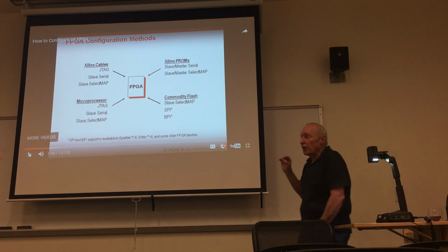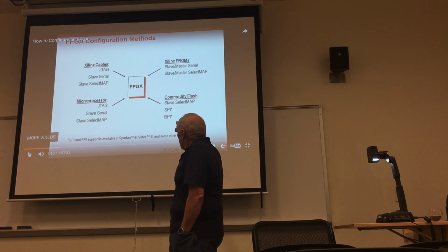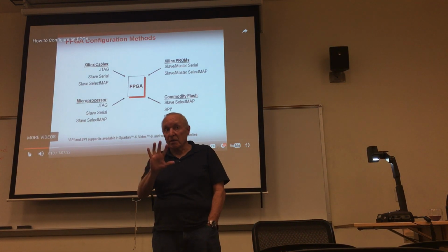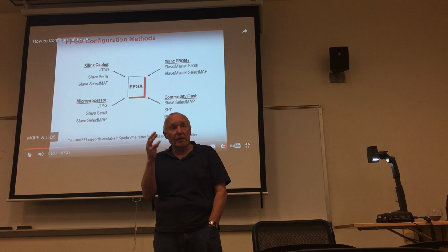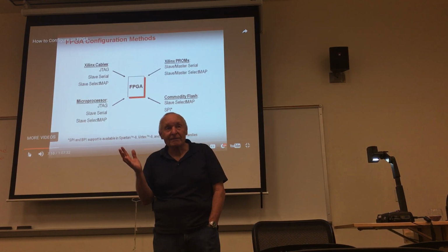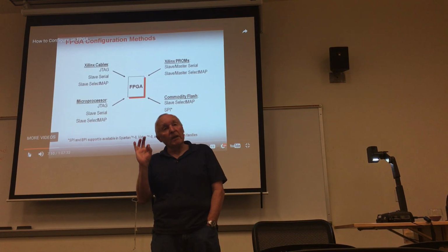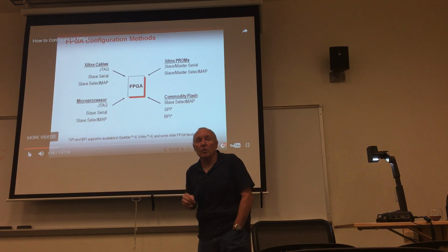And in fact, I'm going to show you an example of the SPI, serial peripheral interface, which is the main one I want to focus on in this class. That memory chip is only 8 pins. It's an 8-pin flash, surface mount technology, so it's in a small outline IC package. It will fit on the tip of my finger. It's that small, but it can contain megabits of configuration information. We'll take a look at one of those.